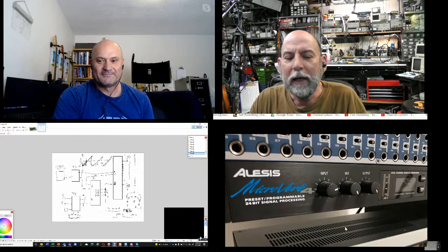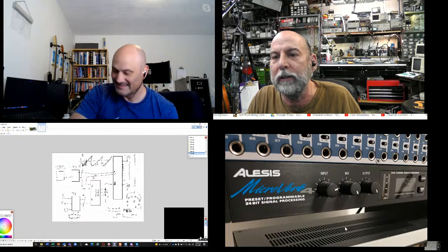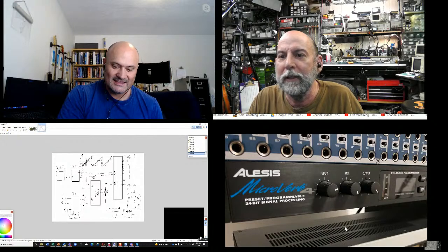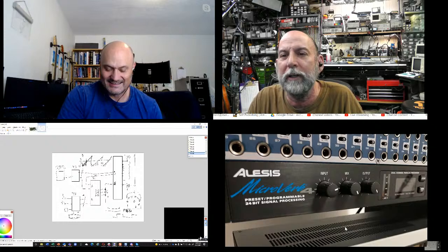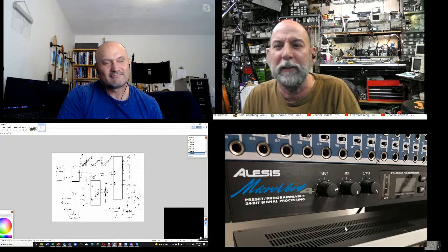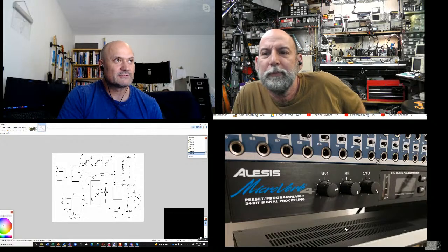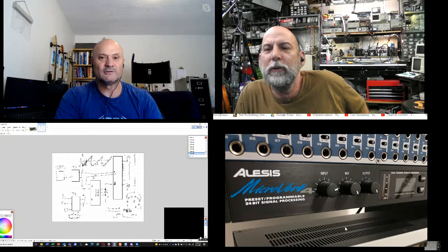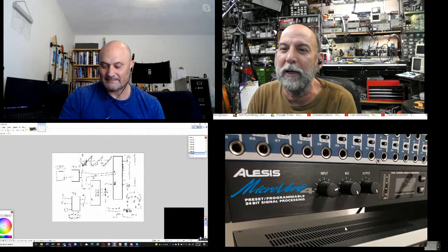Right. I always thought of tubes as, you couldn't hurt them by overdriving either. I'm not saying you couldn't have too much cathode current or something, but with transistor devices, you had to be aware of safe area operation, things like that. But with the tube, it was way more forgiving. In a preamp sense, they are, but tubes in power amps do give out. They don't last. Well, that's why I meant cathode current. Yeah. You get cherry red plates if you're not careful.